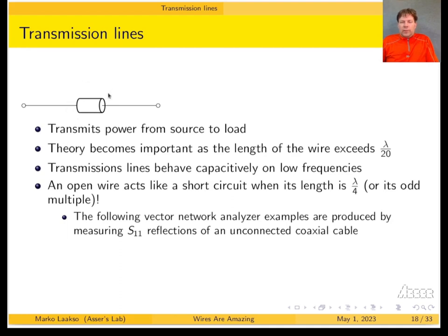it's important to consider those waves. And the theory becomes important as the length of the wire exceeds, well, this is a rough estimate, but it's good to consider wave theory and the transmission line theory if you are at the order of 1/20th of the wavelength. So the higher the frequency, the shorter transmission lines become significant.